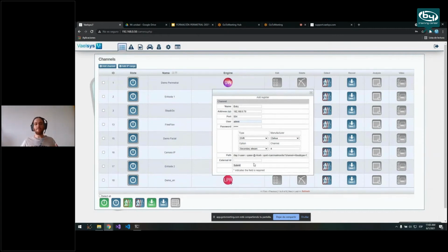So the usual configuration is a camera sending video to a DVR. The DVR is continuously recording the primary stream at the highest quality possible, and in the DVR we have configured a secondary stream with the proper resolution for the detection, and the system will ask, using RTSP,